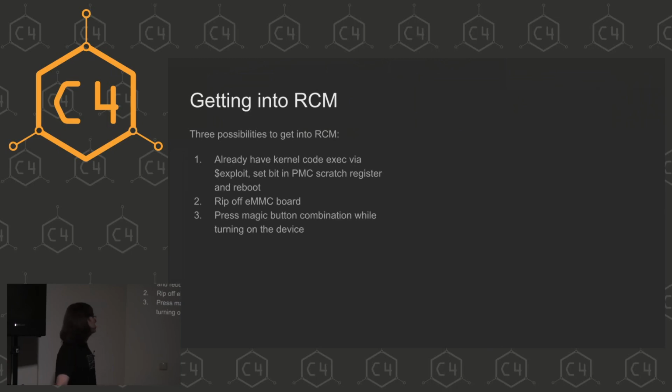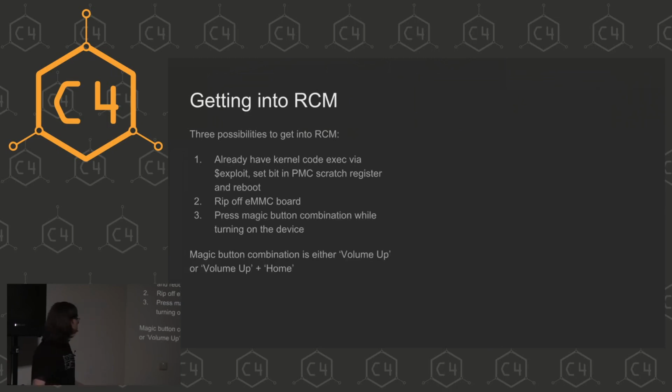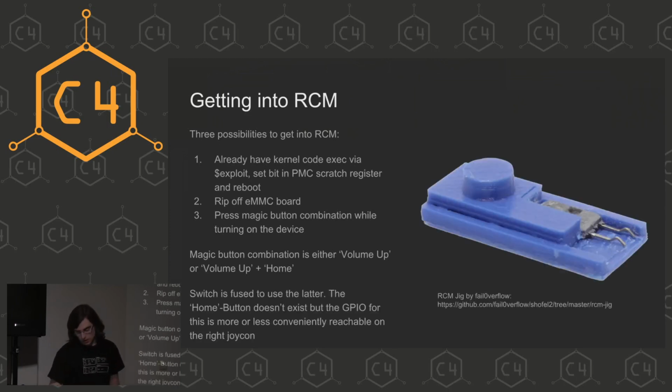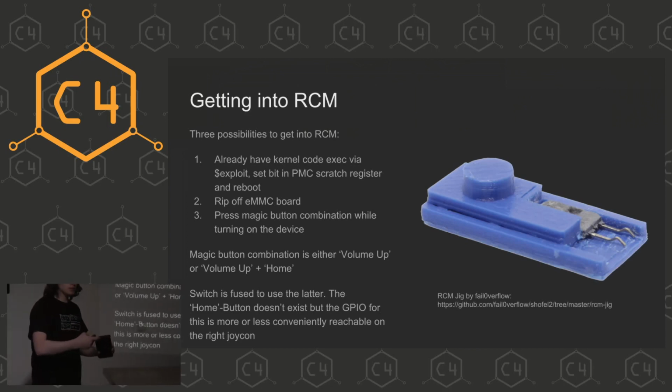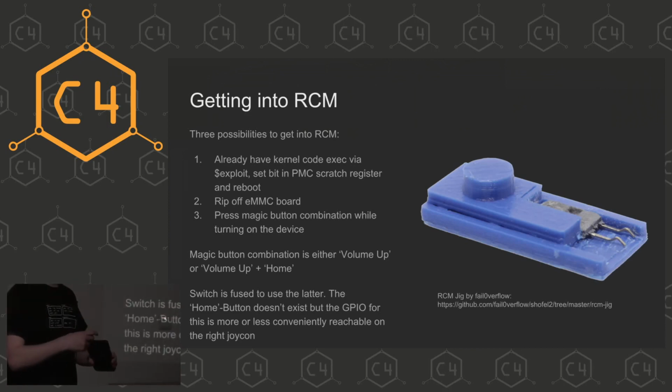Or you press a magic button combination while turning on the device. The magic button combination is configurable. Either it's volume up or volume up and the home button while turning the thing on. The switch is configured for the latter, so the home button doesn't exist. But Failoverflow found out that here on the side, on the right Joy-Con, where this Joy-Con actually connects down here to some pins, there is this pin for the home button.